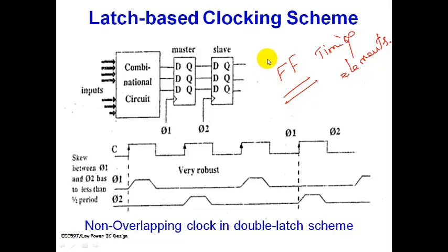We had so many advantages of this master slave flip-flop structure. The master would be operated by the phi 1 when it would be going positive, and when this goes negative, this would no more be responding to the signal whatever I have here. Instead, the phi 2, whatever be the output was at this point, would take it up and it would go for working. That is what we had been studying as the master slave flip-flop.